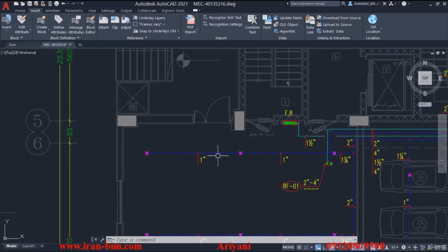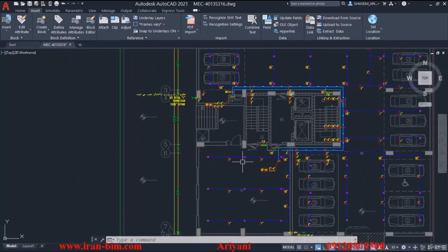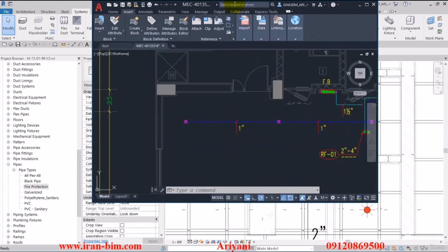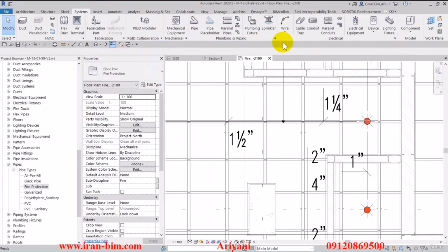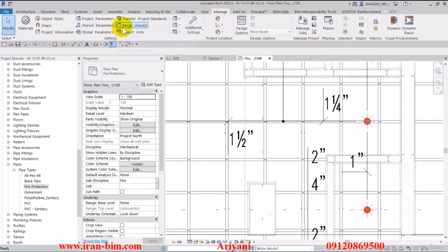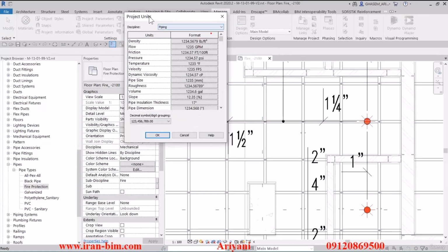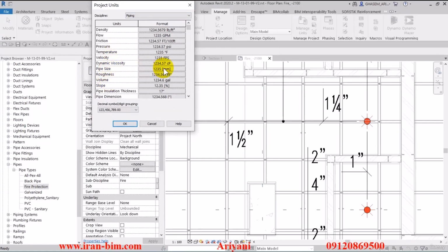Now, because of this, Revit cannot handle 2 units at the same time in the same file. In order to prevent any issues and have them either as inches or millimeters, you'll need to distinguish them yourselves beforehand. For example, let's say we have a 5-layer pipe using millimeters as units.